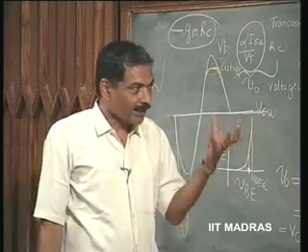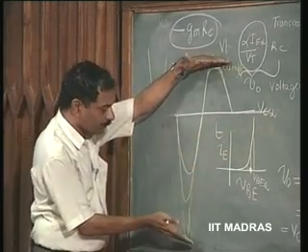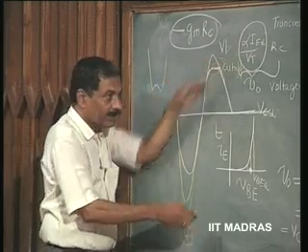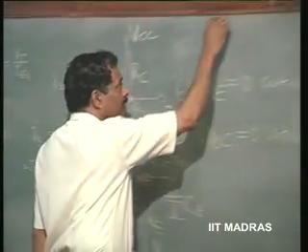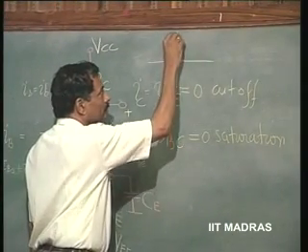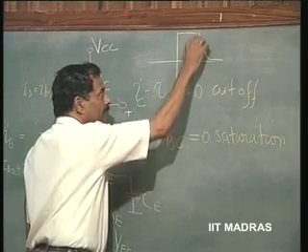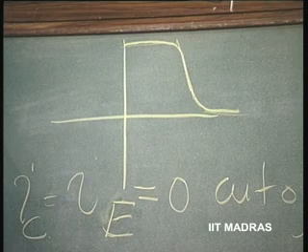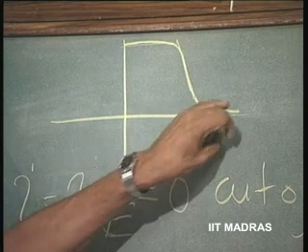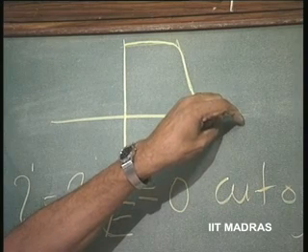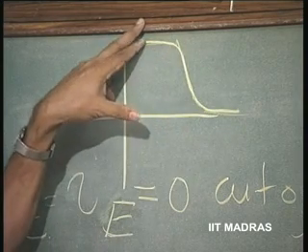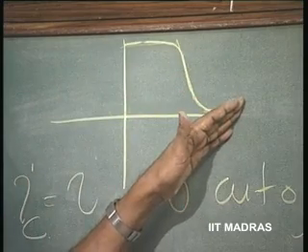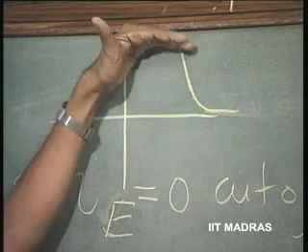Is this clear? So, when you are considering the amplifier, you will now bother about these points as saturation points, where the amplifier characteristic will be just this. This is the linear characteristic, nonlinear. These are the two saturation levels. At this point, the transistor is going to saturation. At this point, the transistor has gone to cutoff. But as far as the amplifier itself is concerned, this whole thing is called saturation nonlinearity. Limiting nonlinearity it is called.